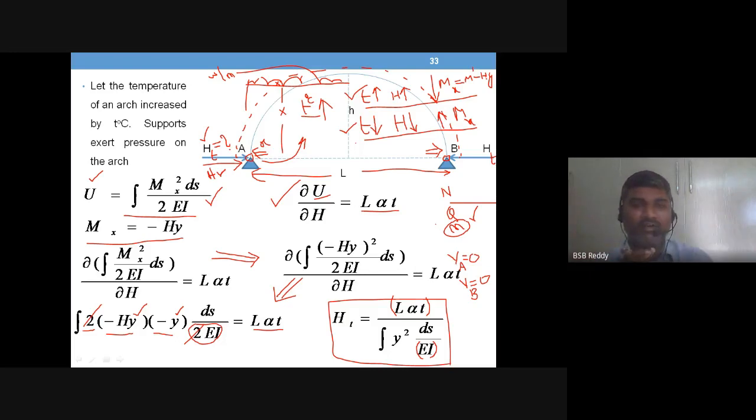It's all the practical aspect of it. Okay, so you have designed for some value, and at a later point of time you observe temperature changes are heavy, and then you have to calculate what will be the change in bending moment, whether it is within allowable limits or not. The factor of safety that you have used, is it within that factor of safety limits, or is it going beyond? Okay, all that, as an engineer you have to worry about a lot when you are checking its safety or critical condition.